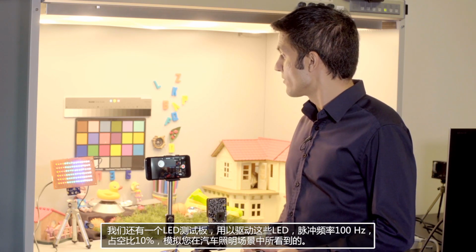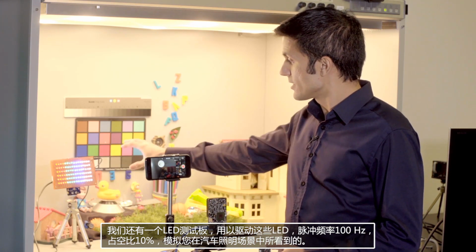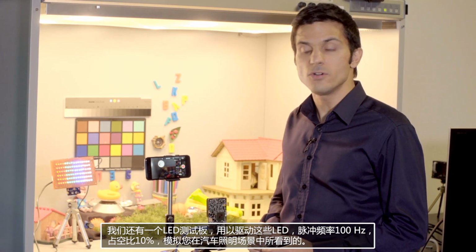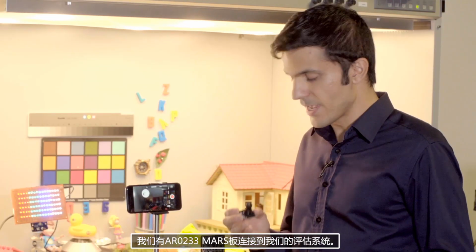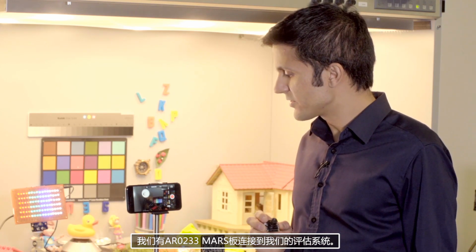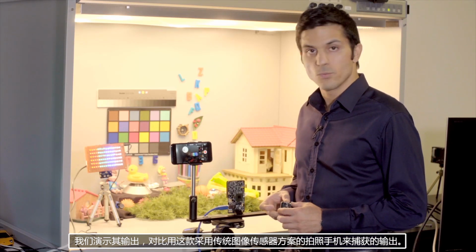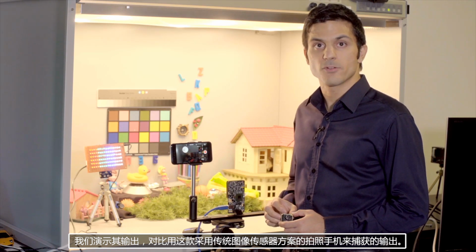So here we have a test setup inside our light box to emulate a high dynamic range scene. We also have an LED test board that we're using to drive these LEDs to be pulsing at 100 Hertz with 10% duty cycle to emulate what you'd see in an automotive lighting environment. And we have the AR0233 Mars board connected to our evaluation system. And we're showing the output of that compared to what you would see with a traditional image sensor solution that we're using this camera phone to capture.